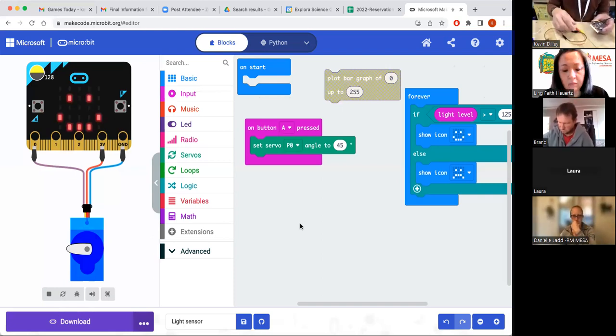So it shows here on the wiring diagram that one of them, the one here, goes to ground, the one on the other side goes to 0 pin, and then the center wire goes to 3 volts. Okay, so let's get these connected to ground, to 0 pin, and to 3 volts.